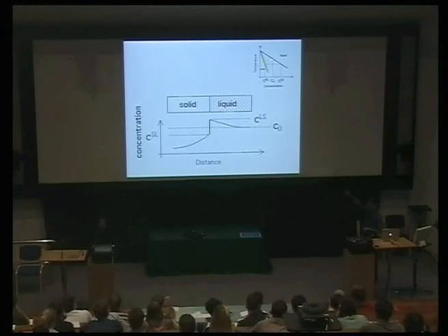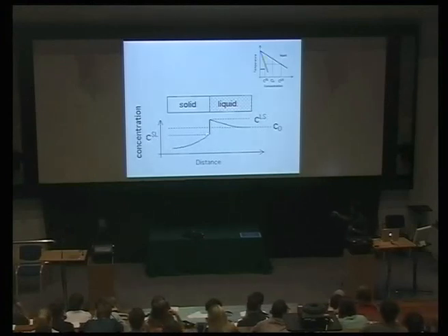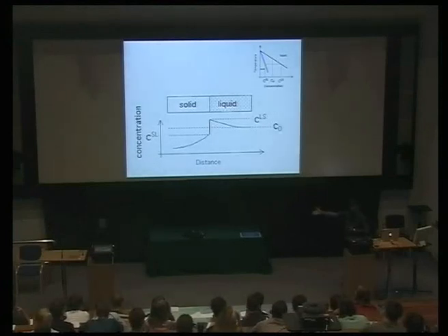Simply because we started solidification at this temperature, and the composition of the solid moves along that phase boundary as we cool. Okay? So here is our bar, which is solidifying. At any given temperature in the solidification process, the tie line defines the compositions at the interface, and the far field composition is C naught. Okay? So we're assuming that it extends a long distance.